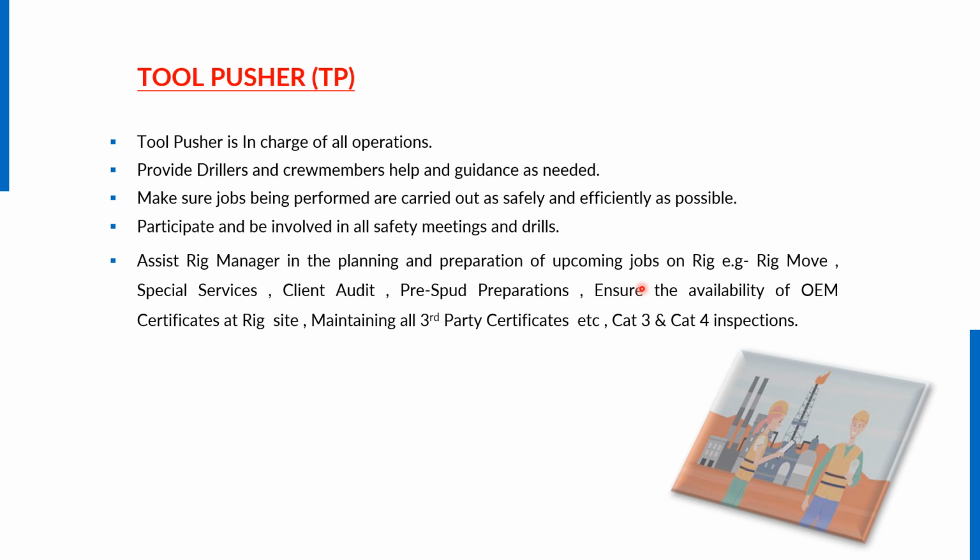Lifting is the most dangerous in the whole cycle of the rig move, because the rig move is not just the move. The rig move is complete only when there is a rig down, then the rig move, and then the rig up. These three activities complete the rig move. That's why it is a very dangerous, hazardous as well as hectic operation. In previous days, there are many case studies with fatalities or accidents due to improper ways of working during the rig move. So all personnel, especially the safety professional, have to pay special heed during the rig move.